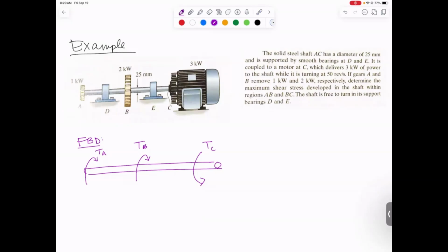We're not going to draw any reaction moments at those bearings. We're only going to draw the reaction forces, which will be perpendicular to the shaft. So I'll have a DZ upward, and DX outward, assuming the shaft is lined up with the y-axis. And then we would also have ZX. And let's assume one of these is a thrust bearing and the other one is not. So if it is my thrust bearing, you would have also EY on there. And that'll work for a free body diagram.